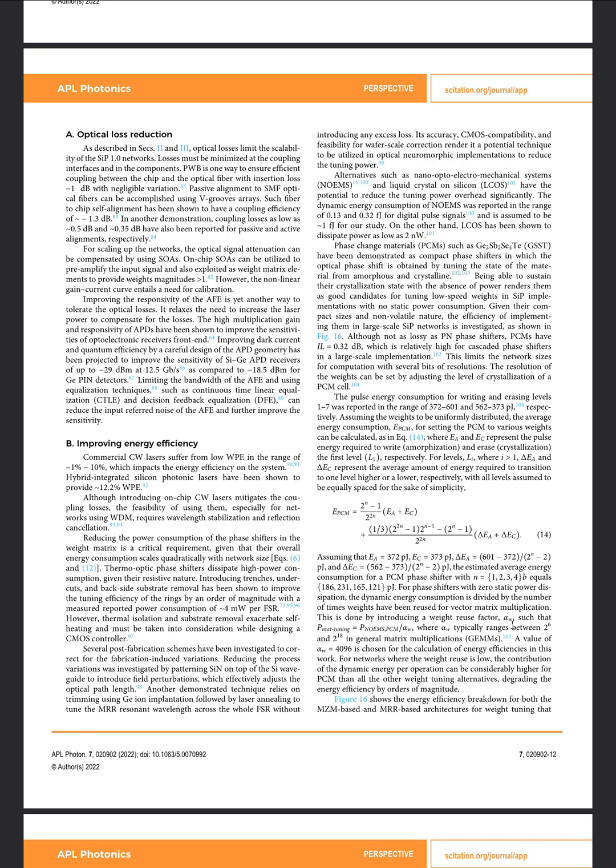Going back to the point I made earlier, microring resonators use heaters to tune themselves, but they are very sensitive to heat, and exacerbating self-heating and thermal isolation is not good, and as a result, further research should be done in removing these heaters as a tuning method.